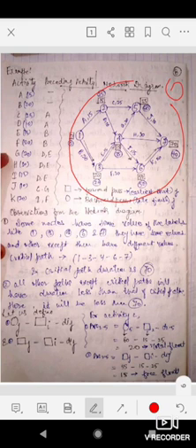We have also mentioned the earliest finish time and latest finish time, earliest start time and latest start time. The values in the square are telling us the earliest start time. So we have shown here that earliest start time for activity C is 15, and latest start time is 25. If you look at node 5, earliest finish time is 55 and latest finish time is 60.